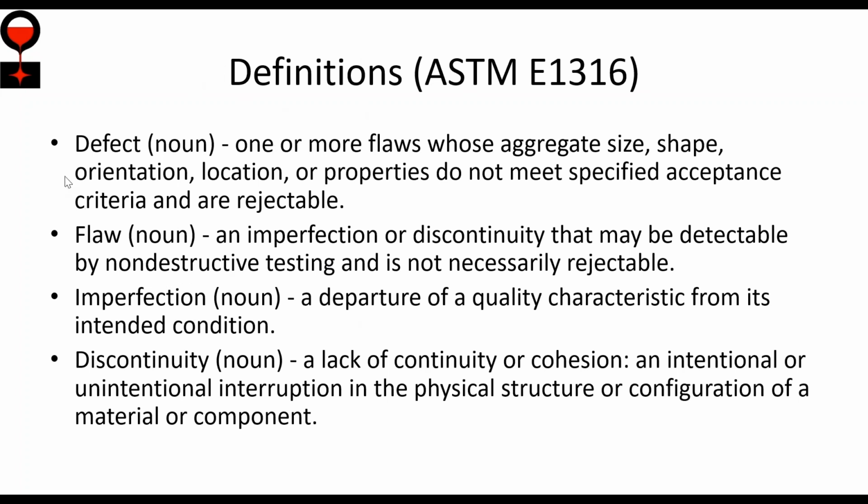One of the challenges we face is everybody talks as though once I find something in non-destructive testing, that's a defect. It's not a defect until I try and transfer ownership to you. And so what I'm really doing is trying to meet your quality standard. And I find conditions, whether it's a lack of heat treatment, mechanical properties, a lack of dimensional conformance, or something that doesn't meet your non-destructive testing, I continue to work until I meet all of your requirements, and that's why I do this final inspection.